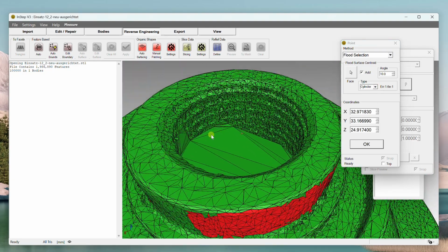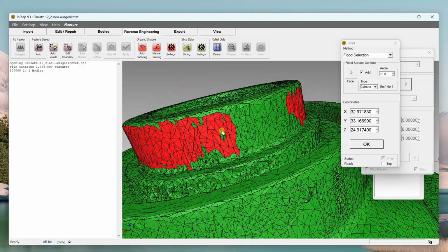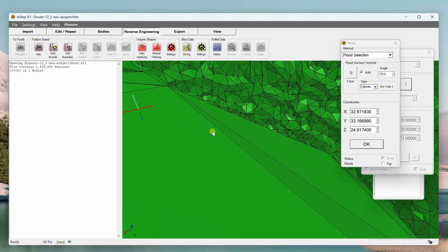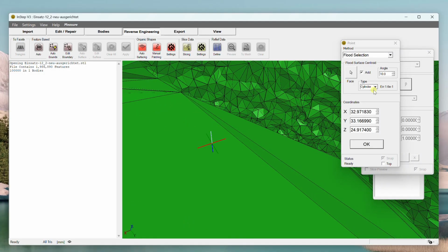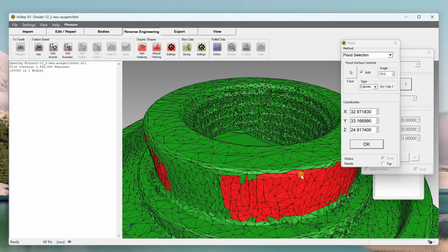What we are getting is a best fit cylinder that passes through these facets, and the average height of that cylinder is where this preview point is being placed. And we get an error. This is the maximum error. So 0.16, or 1.6 times 10 to the minus 1, is the distance between any one point and that center. And when I say any one point, the largest distance out of all of these is this value.